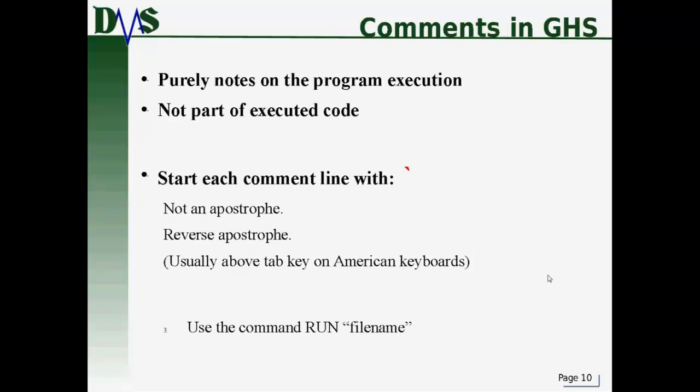If you open up some of these run files, one of the things you might notice in there is that there are comments in the run files. Comments are really handy. They are just notes that the programmer wrote. It's not part of the executed code. It's just notes on the execution of it. So little comments in there that the programmer wrote to each other, memory joggers, explanations of what the code is doing, handy things like that. And they're marked with a reverse apostrophe. So any line that starts with a reverse apostrophe is a comment line. Now take a second to find the reversed apostrophe on your keyboard, because it's not the normal apostrophe.